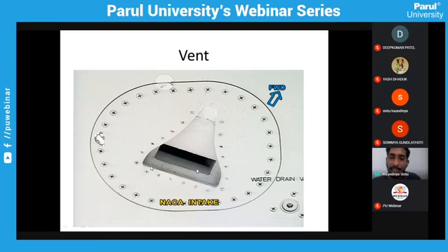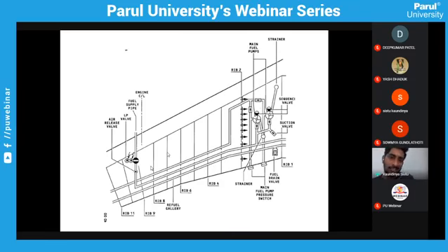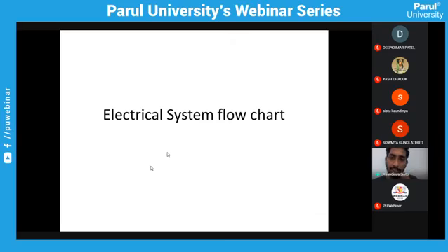This is where the air intake goes into the fuel tanks. The amount of fuel used, that volume, an equal amount of air should be filled into the tank so that it will have a continuous flow. Otherwise, bubbles will be formed, and that leads to fire at a certain point. So that's what the air intake vent is. These are in-depth parts of the fuel systems, strainers, fuel pumps, because even when you have a fuel pump, there are release valves. Many things come into the picture. We can discuss this later, or in any other sessions.